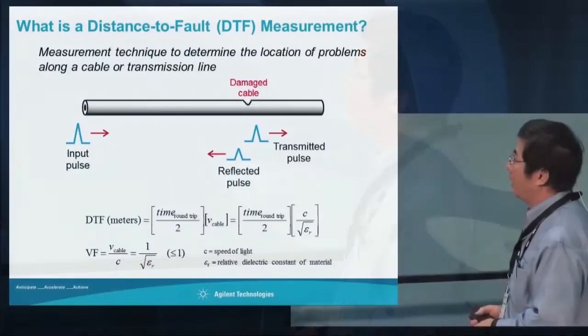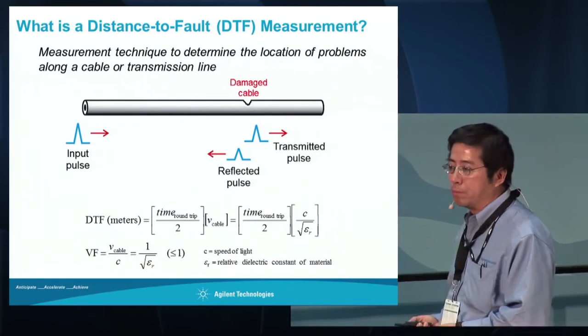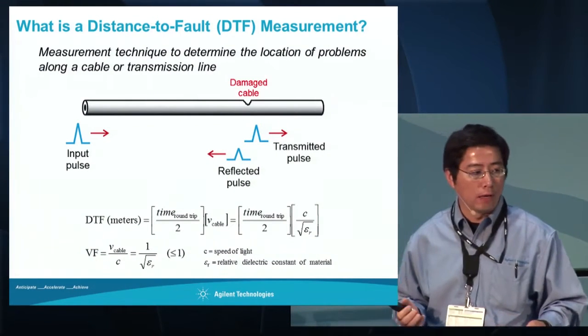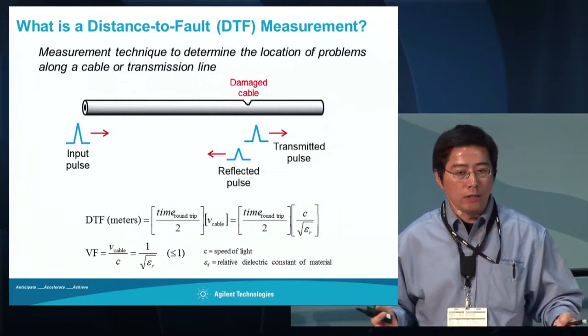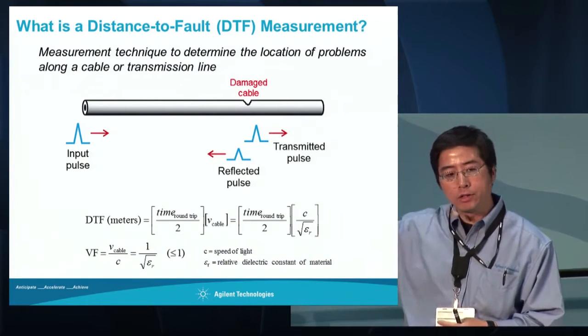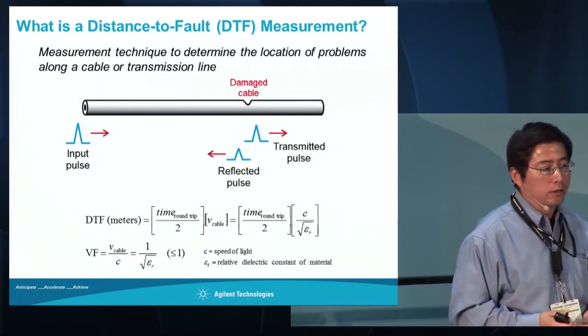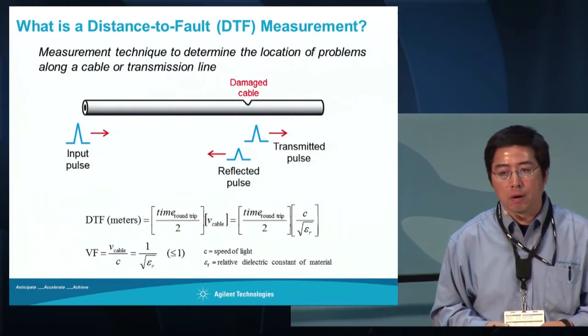Okay, just now we talked about the frequency domain, return loss and VSWR, which are essentially the same. Now let's talk about time domain. In the cable antenna industry, we typically don't say time domain, we talk about distance to fault, which is a half of the time domain. Why is it important? In the early days, you had a cable and an antenna, and you could easily figure out which component was the problem.